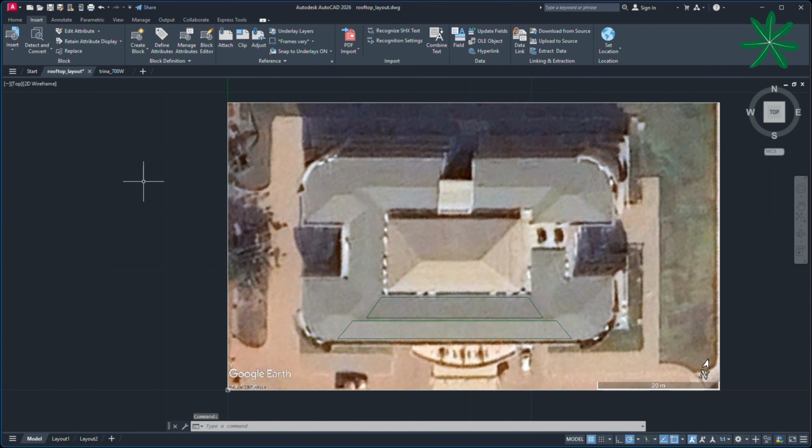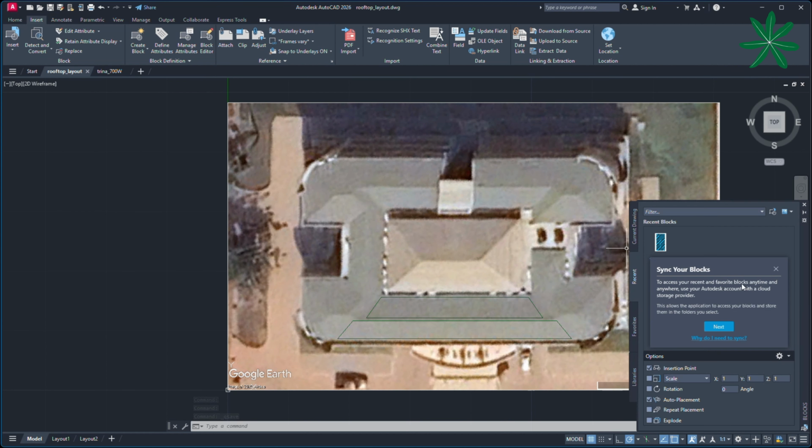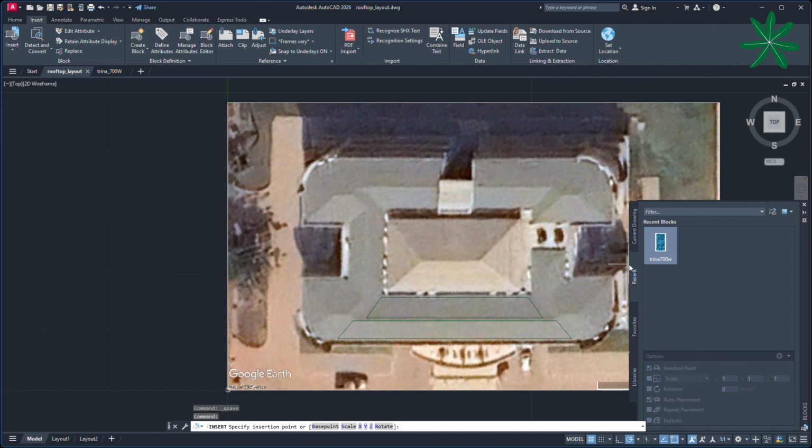So after we've defined the area within which we are placing our panels, we go on and import our panel. So we go to the block and then select the panel. But you can see that from the size of the block and from our roof area, we cannot stack it vertically unless we align it horizontally. So let's place it anywhere and proceed to align it horizontally.